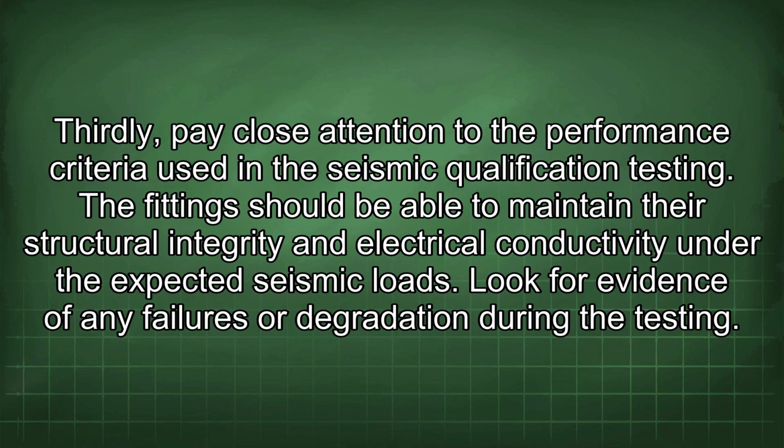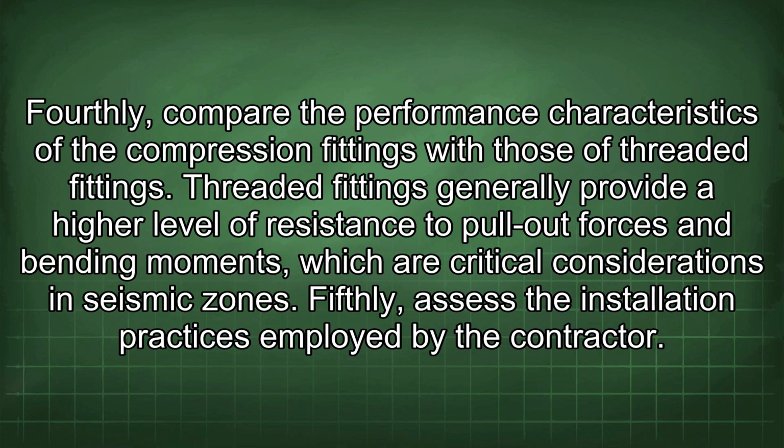Thirdly, pay close attention to the performance criteria used in the seismic qualification testing. Fittings should be able to maintain their structural integrity and electrical conductivity under the expected seismic loads. Look for evidence of any failures or degradation during the testing. Fourthly, compare the performance characteristics of the compression fittings with those of threaded fittings. Threaded fittings generally provide a higher level of resistance to pull-out forces and bending moments, which are critical considerations in seismic zones.